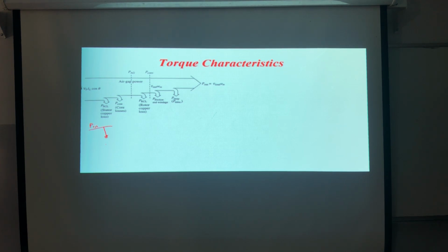So part of the power will be P copper losses of the stator. And this is equal to what? Yeah, it's 3 because I'm having 3 phases. 3 I1, or I stator, squared, RS, correct? Sometimes the core losses are already augmented here. So we say that this one is augmented here with the copper losses. Yeah? So in this case, what will we have? The power in the air gap.